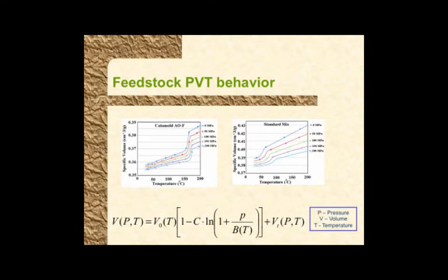Same thing, if you change the amount of powder, this is going to change as well to some extent. The more powder you have, the less compressible the material. Polymers are more compressible than powders, and so the greater the volume fraction, just like rheology changed, compressibility is going to change and shrinkage is going to change.